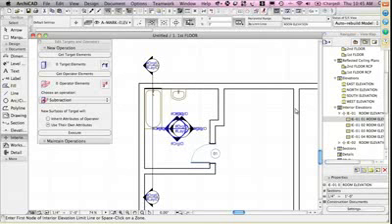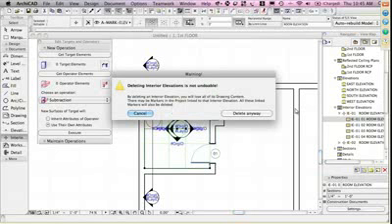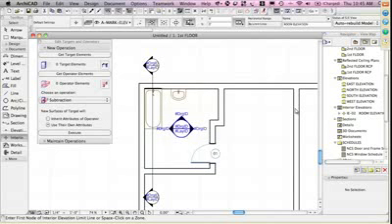Let me get rid of the original elevation that I had here, and you can see this particular one is only facing the 3 sides, and maybe that's appropriate because this 4th side has no features that we need to show in a drawing. So Heather, I hope that answers that question, that you can actually draw whatever shape you find useful with that polygon option. You don't have to follow the entire room outline. You can do it manually.